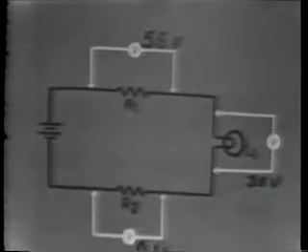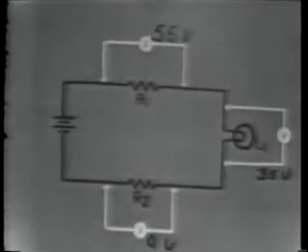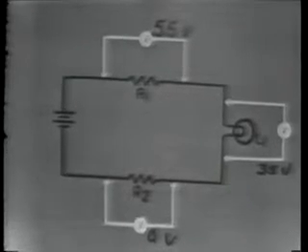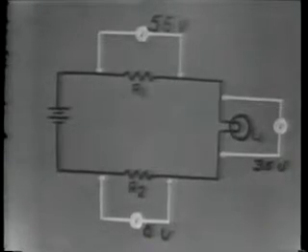If it was open, we'd read the applied voltage and would not have any voltage indicated across R1 or L1. There cannot be any voltage across a short, since a short is a very low resistance. Therefore, R2 is shorted. Then in this circuit, we have one short and no open components.